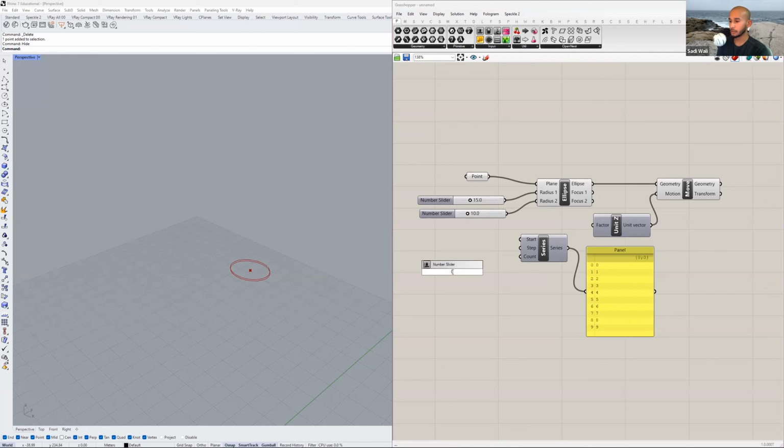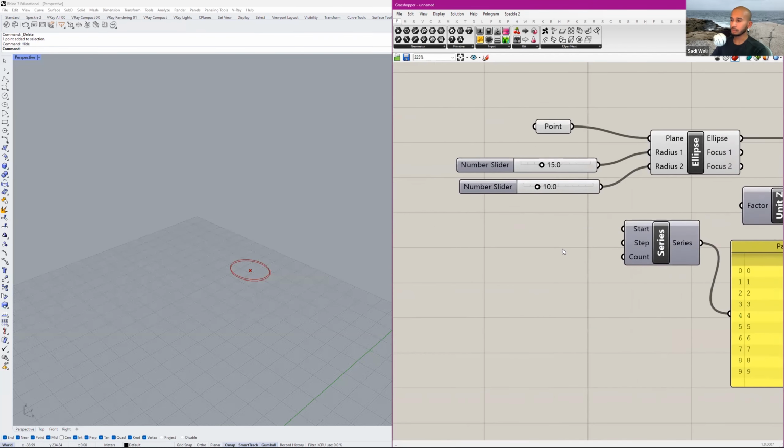So we'll create 2 sliders. An easy, quick shortcut way to create a slider is to first put in your lower limit. It's going to be 0 for us. Then put in a less than sign, and then put in your upper limit. In our case, since we have 50 floors max, I'm just going to put in 50. And that creates a slider that goes from 0 to 50.